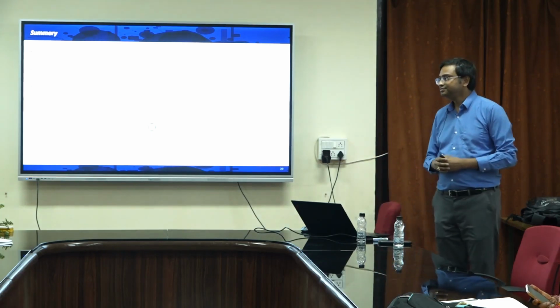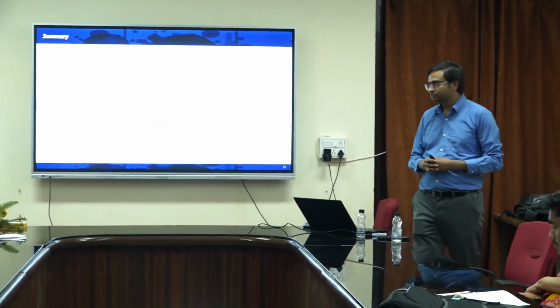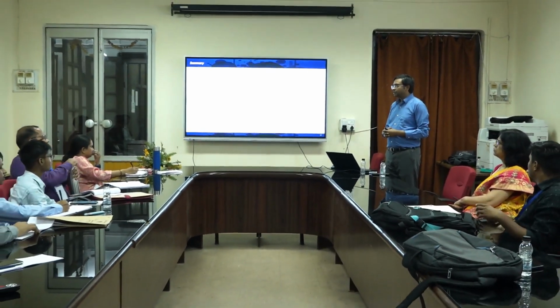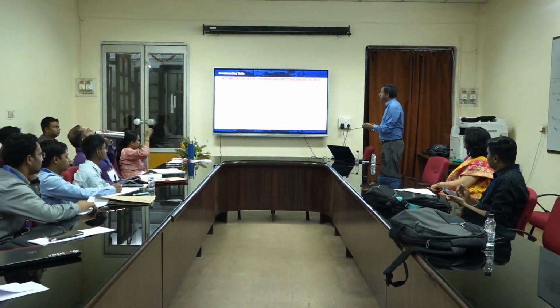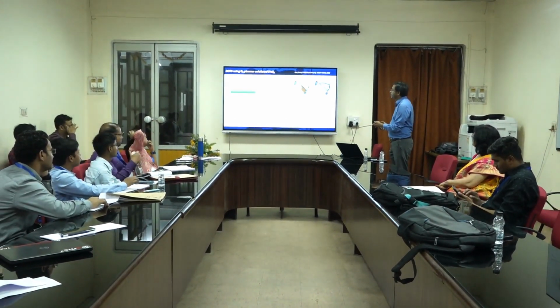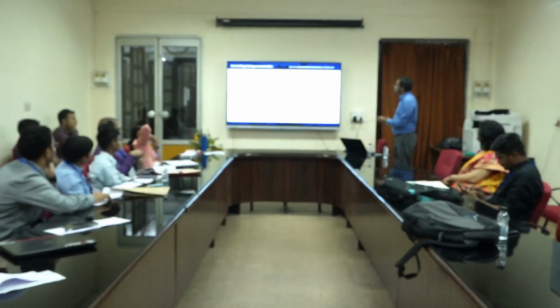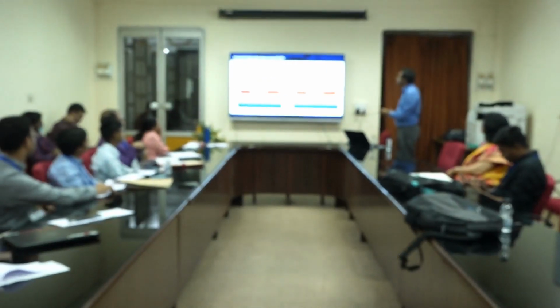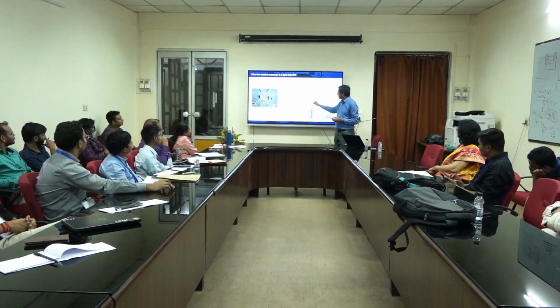Compared to vanadium and platinum, it has a higher on-off ratio. What's the reason? I think it's not about the on-off ratio. If I go back to this slide you're talking about, niobium is actually the best in terms of the contact resistance. You see, it's the lowest contact resistance.